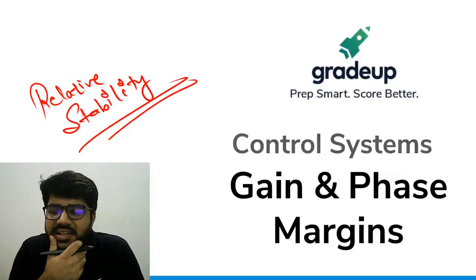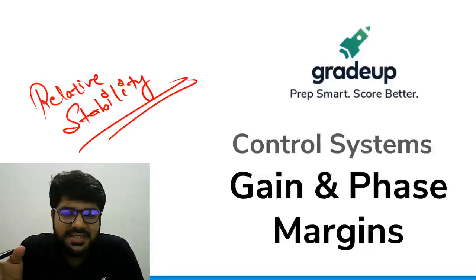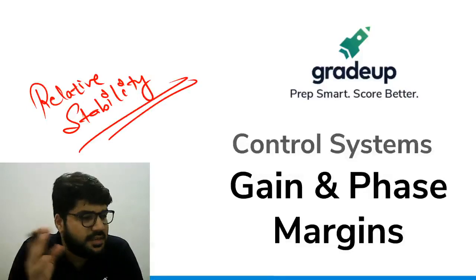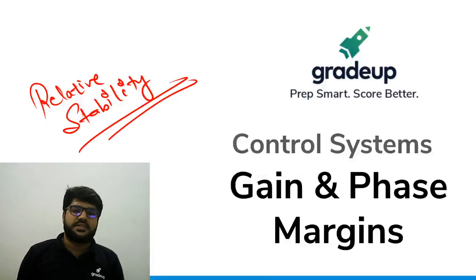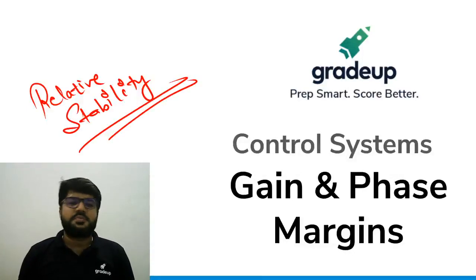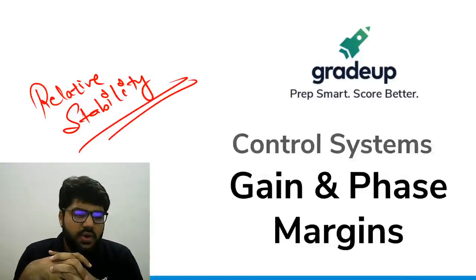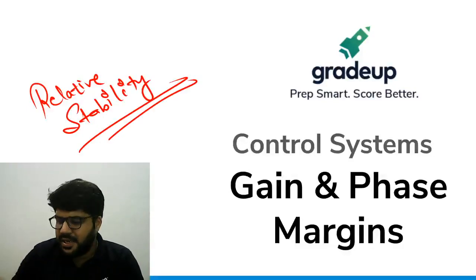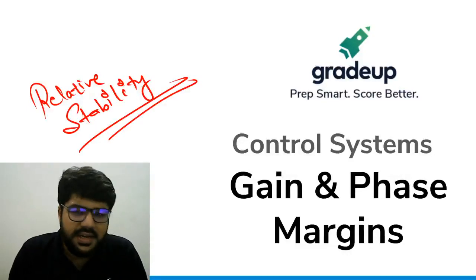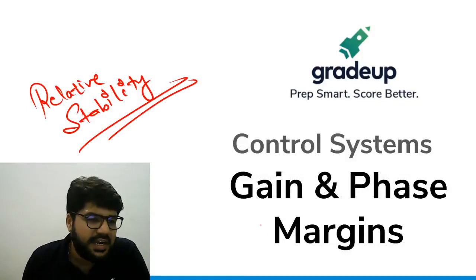Until now we were talking just about checking the stability from the Nyquist plot by the number of encirclements, and we were commenting whether the system is stable or not. But that could also be done by the Routh-Hurwitz analysis. But the Nyquist plot can be extended to compare the stability of two systems. If two systems are stable, which of them is more stable and which is less stable can be compared easily by the Nyquist plot. So we'll extend the concept, and the measures of stability are known as the gain and the phase margins.